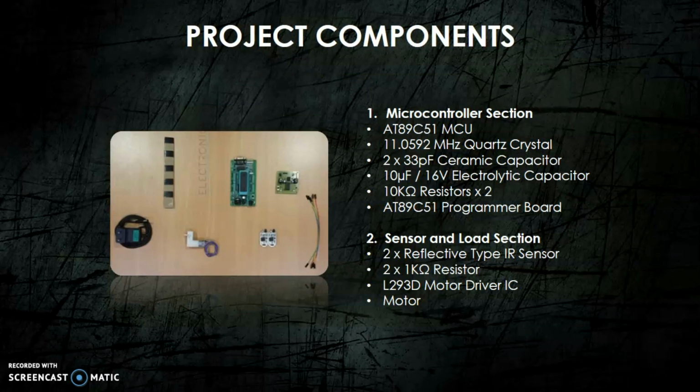The main sections in this project are the microcontroller section, and the sensor and load section. The microcontroller section comes with an AT89C51 microcontroller, an 11.0592 MHz quartz crystal, ceramic capacitors, electrolytic capacitors, resistors, and a programmer board. While the sensor and load section comes with a reflective type IR sensor, 1 kilo ohm resistor, motor driver IC, and motor. The motor driver used in this project is L293D,